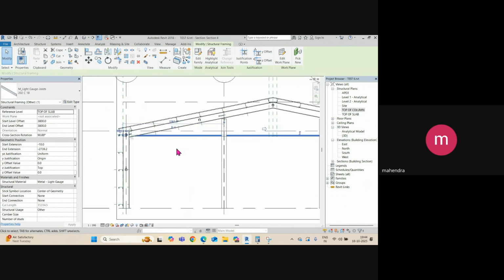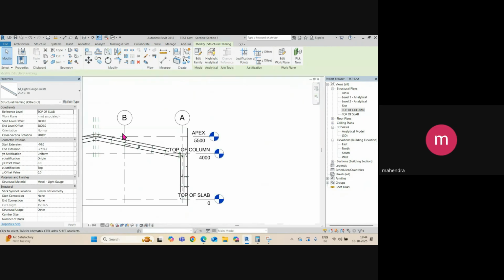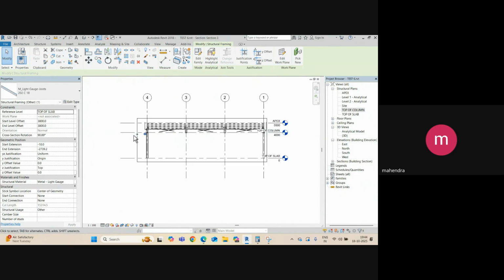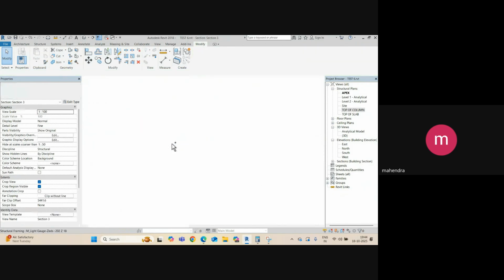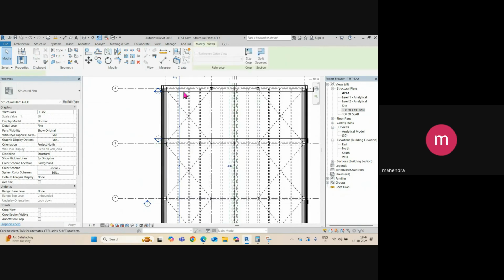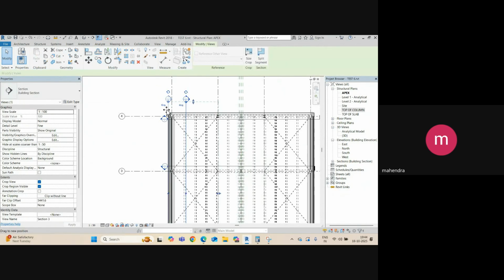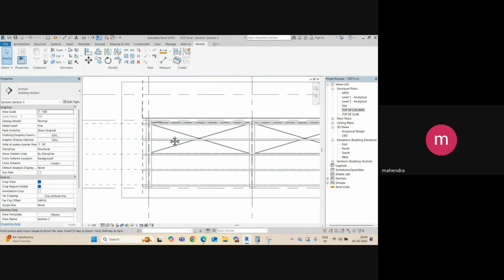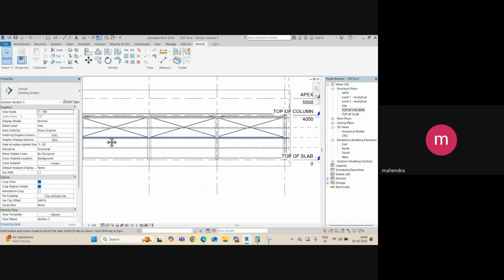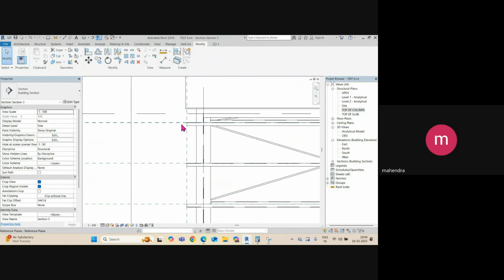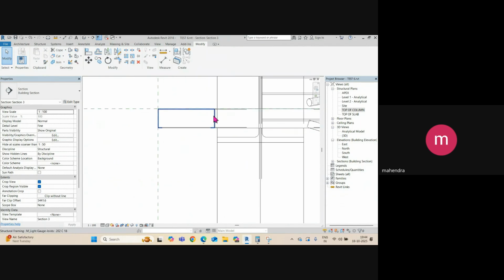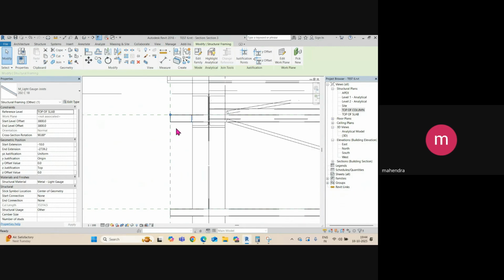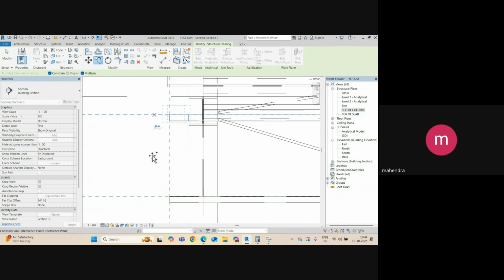We already have a section here, right? In this longitudinal direction also we have one here. But we don't have any base point. So what we need to do, I will just move this section and you can see these purlins and the side guards also here. Then you can copy this. If you go here, this is your other direction purlin. So type CO and then add at all locations.